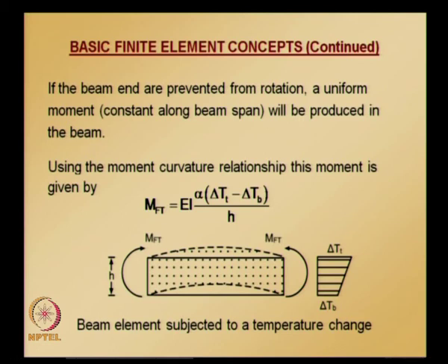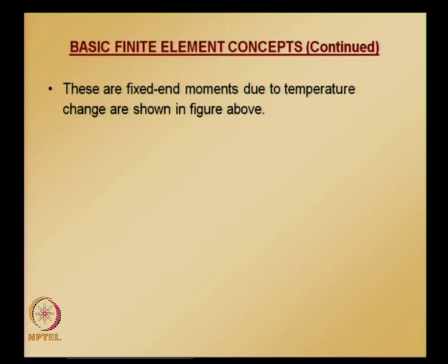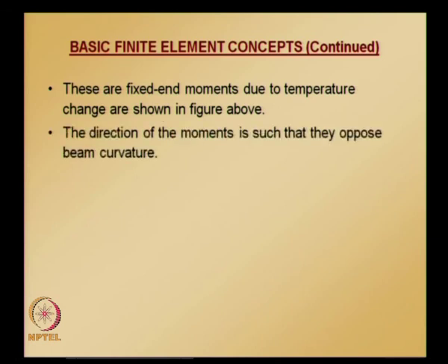And please note that in both cases no shear force will be there. And with the fixed end moments, the remaining analysis is very similar to the distributed load, and the equivalent nodal load vector is equal and opposite to the fixed end forces and moments.